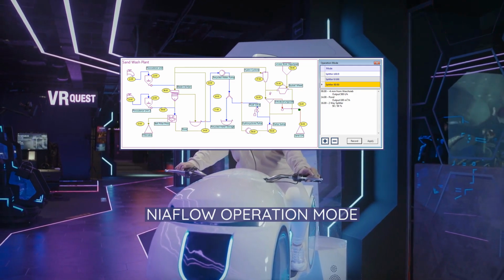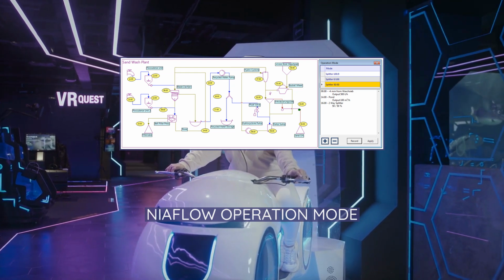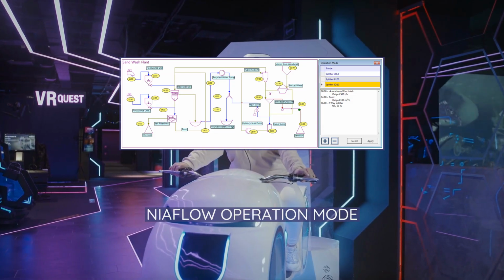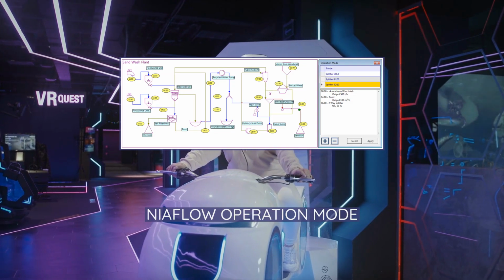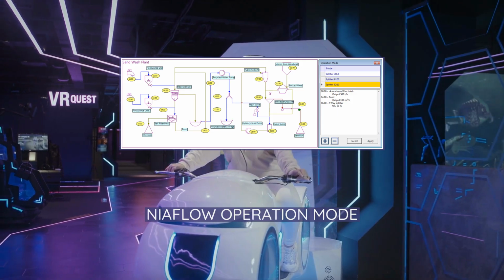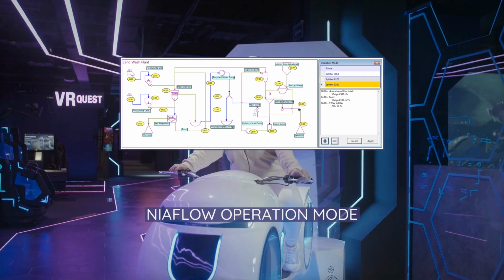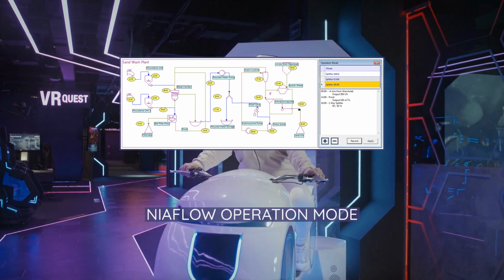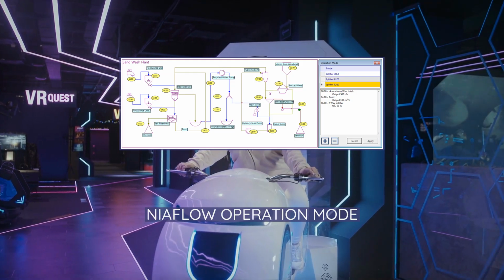Interpolation methods and grids are stored together with the object properties. During blending, all material parameters are recalculated. Depending on the type of parameter, the result can be the sum of the material properties, e.g. TPH, or the weighted average, e.g. temperature. The particle size distribution, PSD, of the blended material is computed by applying all sieves of the materials to the new one and calculating percentages based on the current grid and curve interpolation method.